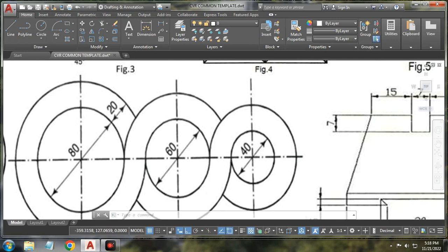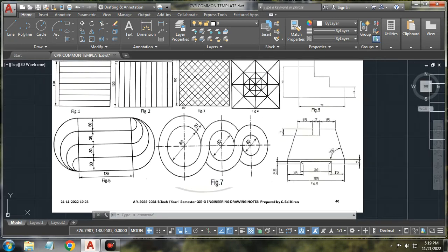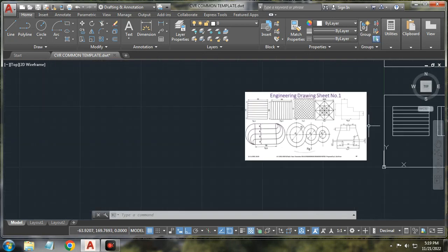So the outer diameter comes as 120: 80, 120. Where this 120 diameter ends, there you have to take a diameter of 60, and this is the center, this is the radius. Again draw a circle, where the outer diameter of this second circle ends, from there you have to take the distance 40, and complete the procedure. Okay, so remember 80, 120, and then you can start.